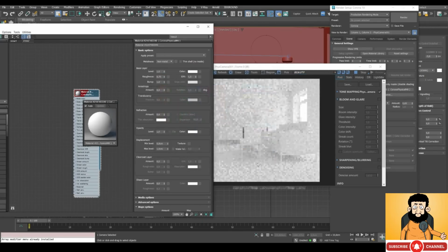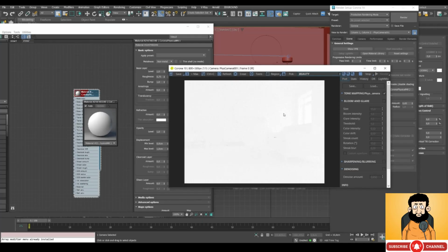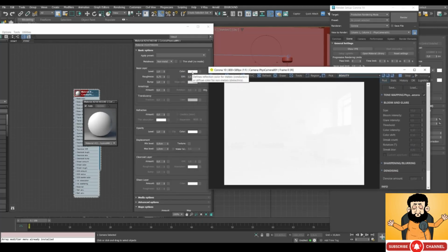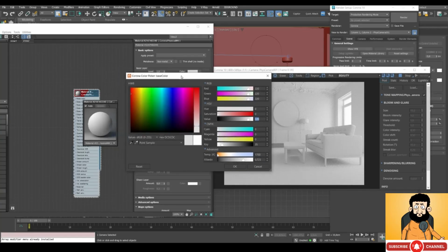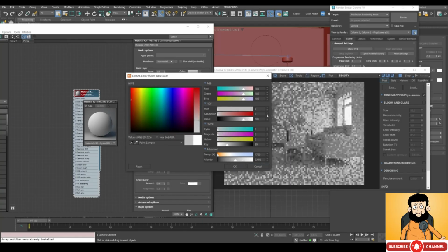And if we increase it by 100%, to 255, the render will become too bright, too highlighted. And this isn't the way it should be. You should always decrease the albedo. So what color value should you choose? For a white material, the optimal color value should be around 200, 220 tops. Or you can change the albedo value here. The whitest material should have the albedo of no more than 0.8. So the higher values are a no-go.